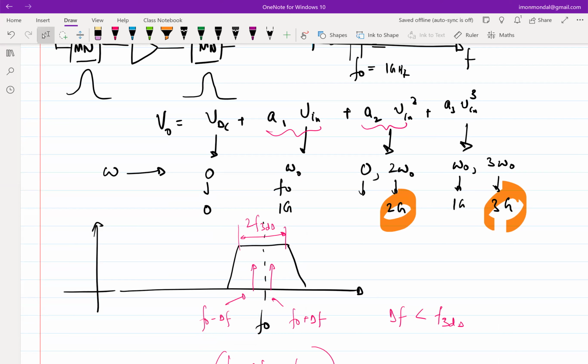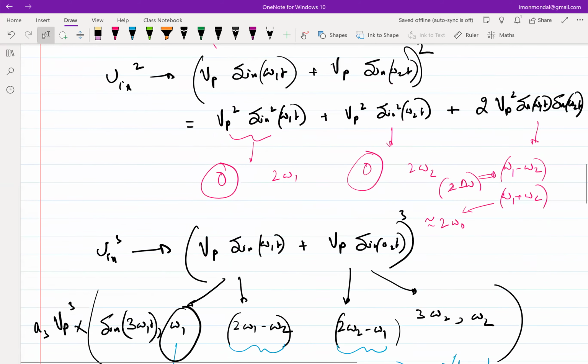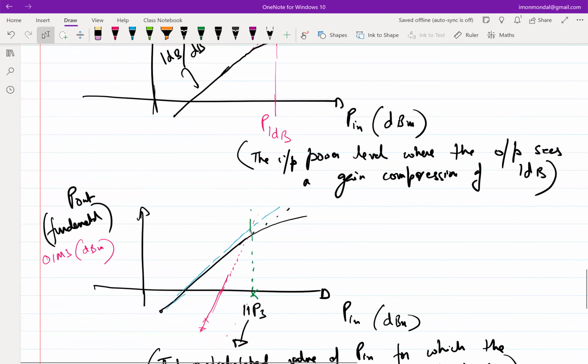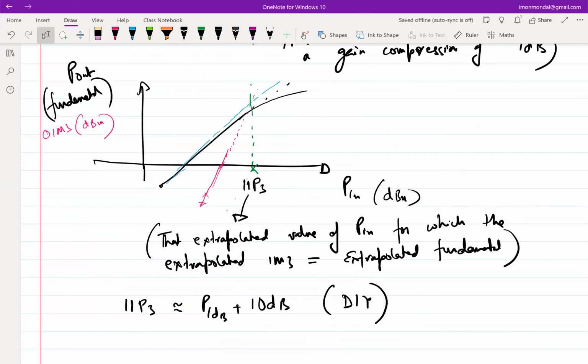It will fall back. So as you keep on increasing the amplitude, those higher order intermodulation terms will fall back on the third, and this will not stay straight, it will wiggle. Sometimes you will see this when you do your inline design simulation, and that's a good observation. You will see that this line, if you keep extrapolating, will sometimes expand, sometimes compress, it will do all sorts of things. And a priori, it is very difficult to understand why. So you'll have to extract each of those Taylor series terms to figure out how it is going to behave around that operating point.